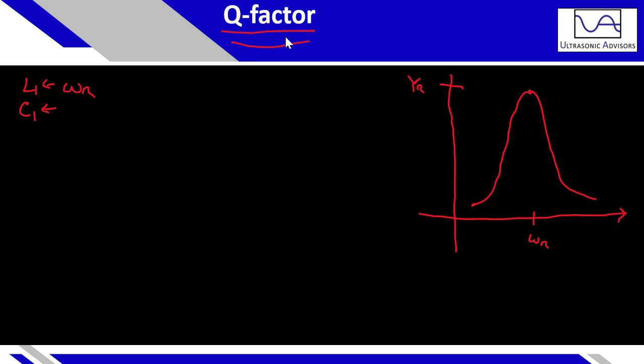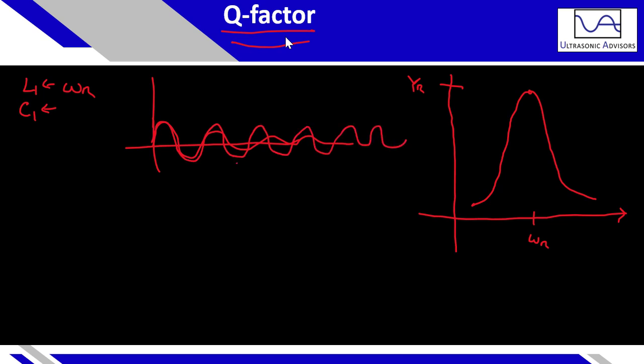Like if you apply a step response to your device, how long will those natural decaying oscillations take? If it's going to take a longer time to decay, that would be a higher quality factor, which has inherently less damping per energy stored, or the resistor is smaller and the inductor and capacitor have larger values, just storing more energy.